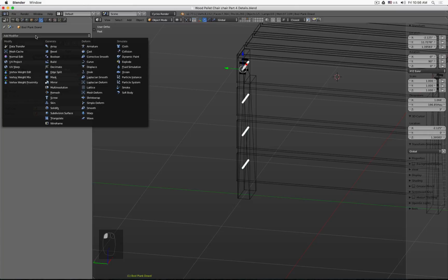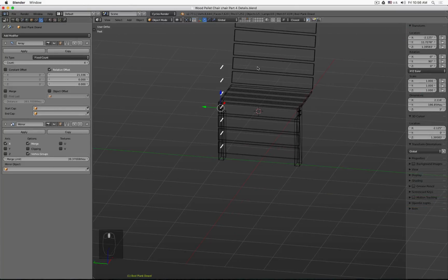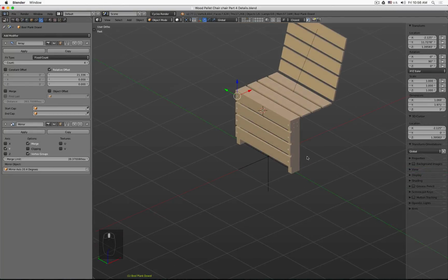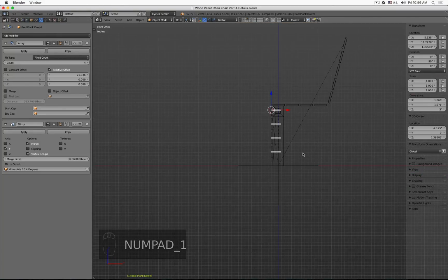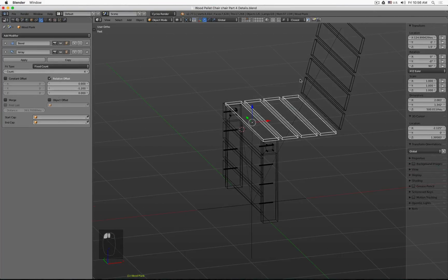So if I now say mirror, I need to have something to mirror over. So in this case, I can't use the object center point, but I need to use the axes we created. So the empty, set the values correct, and there we are. Great. So let's do the same there and there.